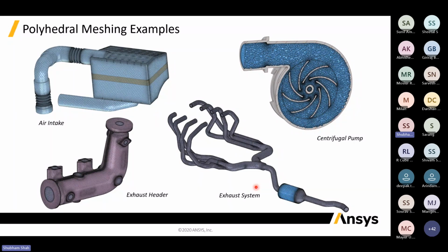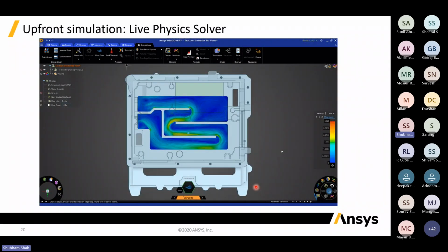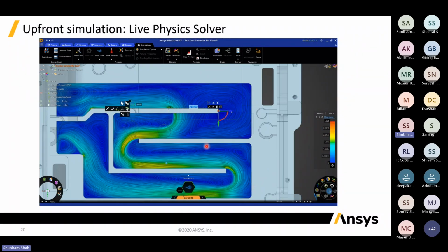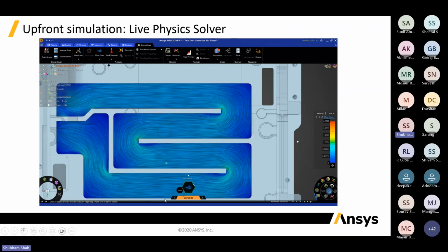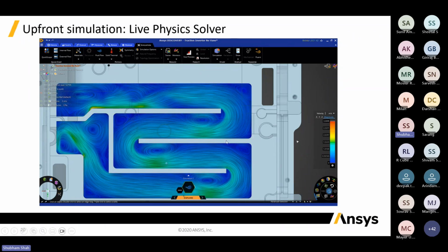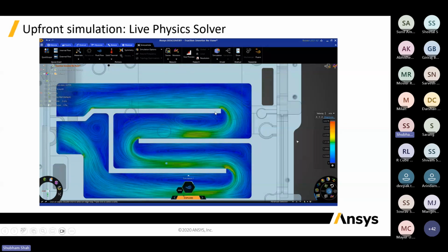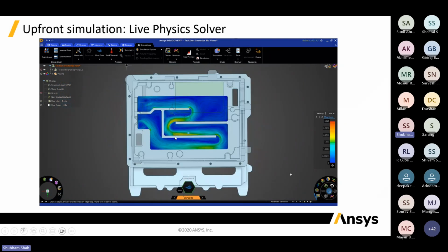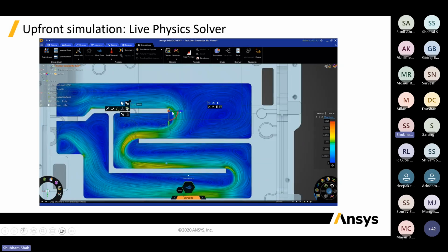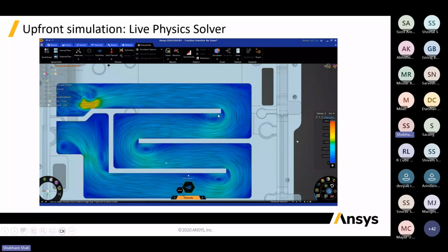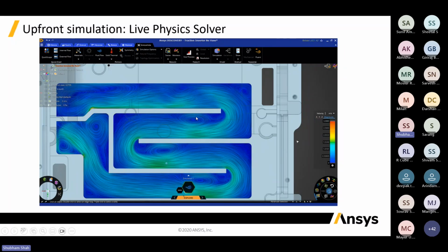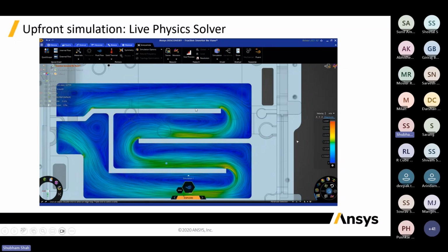This is one of the examples, like I was talking about, where we can change the geometry while the simulation is going on. This is the classic example. For that we have increased the length, and you can see the simulation has not been stopped. We have just dragged and dropped it over here. We have increased the length and the simulation goes on. You can see how the recirculation zone is forming over here. Ideally it was over here, and then we have stretched it up.